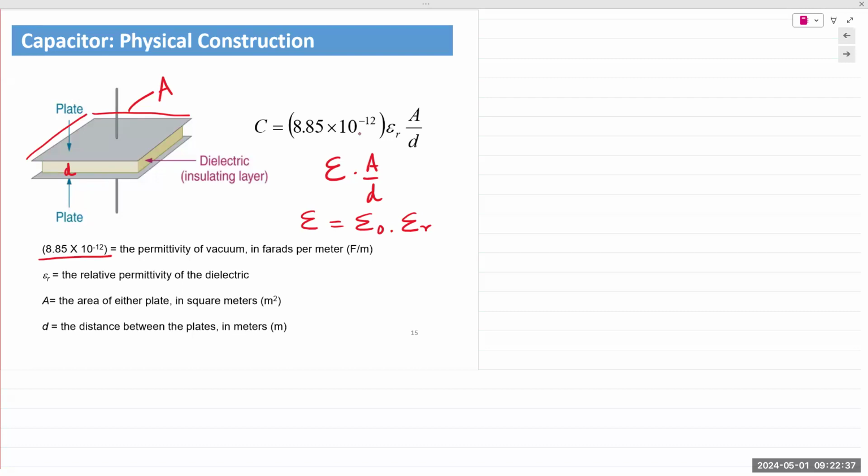So if you have a long conductor, is there any inductance in the straight line or outside of the spiral? There might be, but it's going to be very, very small. It would not affect the actual spiral coil. So when we actually measure the inductance for the spiral coil, we start at the beginning of the first loop and the length ends at the end of the last loop, right? That's how you measure the inductance.